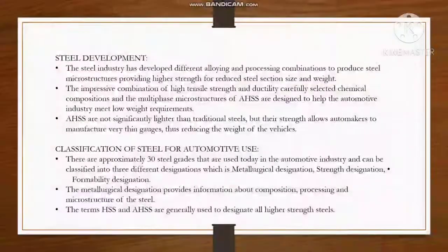What is the steel development? Development is different alloying and process combinations to produce steel microstructures, providing higher strength for reduced steel section size and weight. This combination of high tensile strength and ductility, carefully selected chemical compositions, and the multiple microstructures of AHSS are designed to help the automotive industry meet low weight requirements.